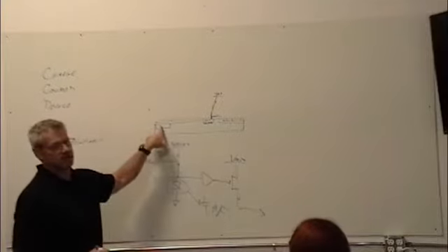A CCD at room temperature, and that might be a lie. If you take a CCD and you bring it down to about freezing, 32 degrees Fahrenheit, it's an amazingly clean device. It does not have to be super cold to be zero noise for all intents and purposes. We're talking statistically like one, maybe a half electrons with a noise statistically. You can't get a half electron. So those are some of the games you play with the CCD.